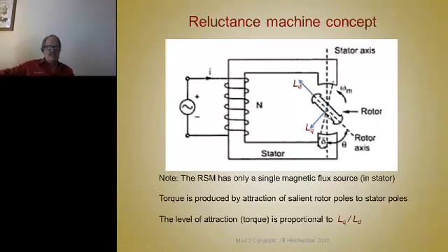When you're generating, you do the opposite. For example, when you're generating, you allow a little current to flow, with a little low voltage across the coil when you're in this position, and then the prime mover rotates it till it's in that position, and then you open this circuit, and you will get an output that's equal to the input times the ratio of these two inductances. That's what you'll see through the flyback diodes in the power converter circuit that go back on the DC rails. You'll get a voltage that's multiplied by this inductance ratio.